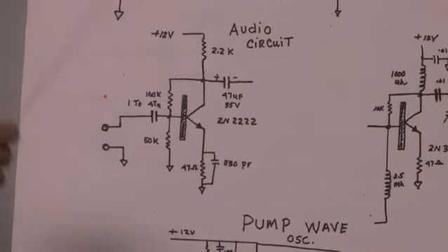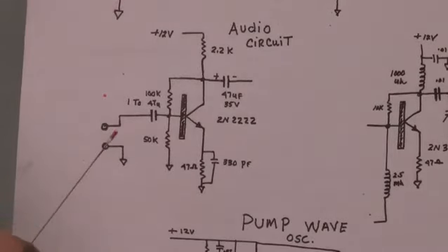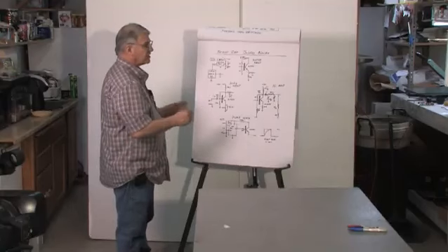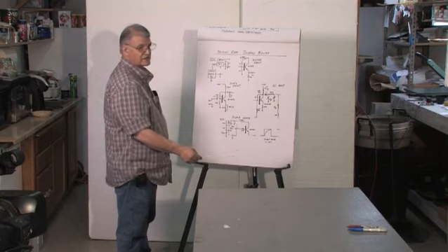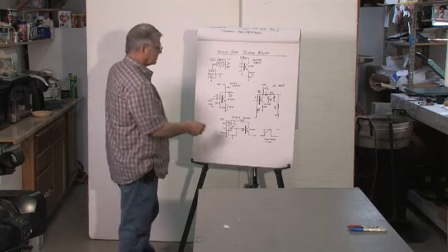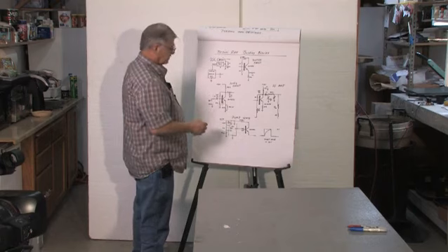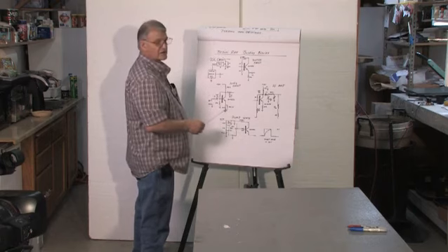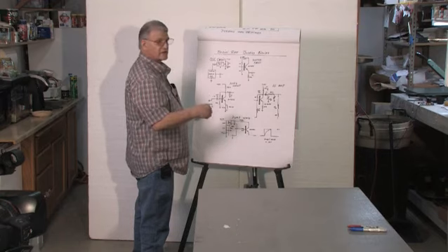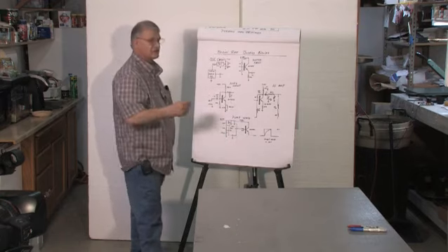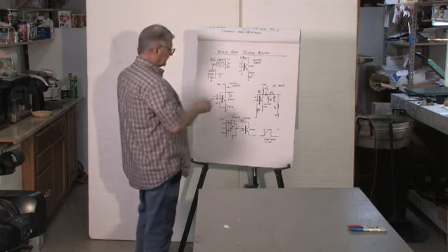But it's not what I would call an audio frequency from 20 to 20 kilohertz, because it's 10 kilohertz to 70 kilohertz is how you're going to get Rife's frequencies. So this amplifier has to be capable of doing 70 kilohertz. In other words, there can't be anything where it's not the same as if it's doing 10 kilohertz. It has to be flat.